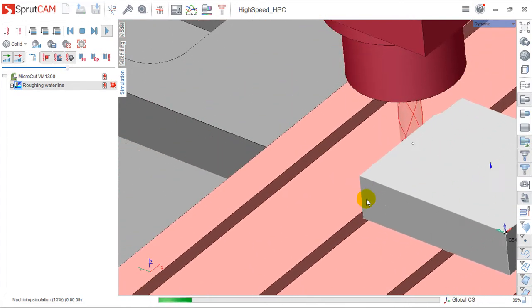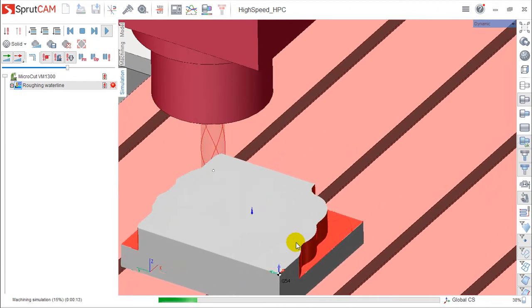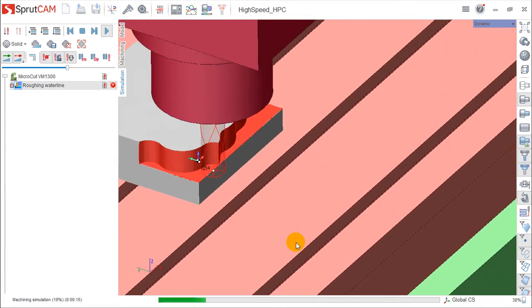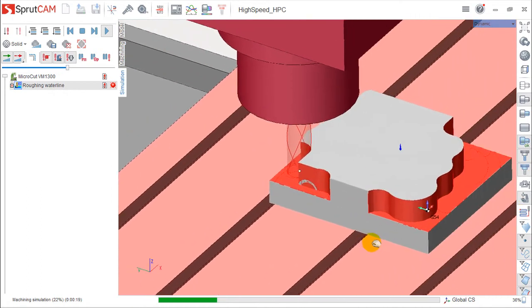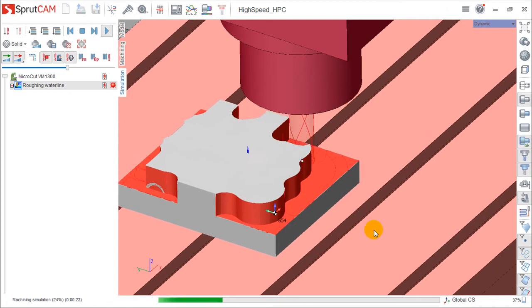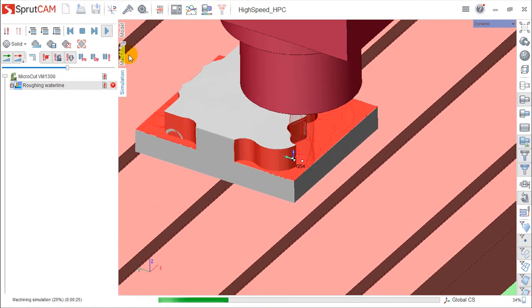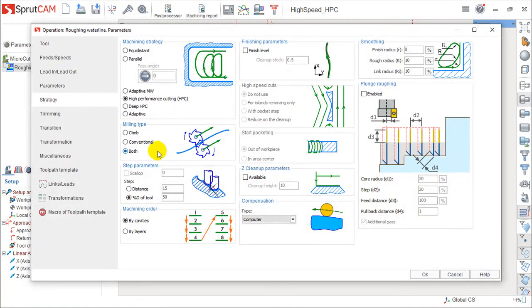Different behavior, even probably if you look firsthand, maybe you think, oh, it's very similar. No, it's not similar, even because you have to consider also in this type of toolpaths a very important topic, which is if we want to do a climbing, a conventional milling type, or both, it depends on the tool you have.